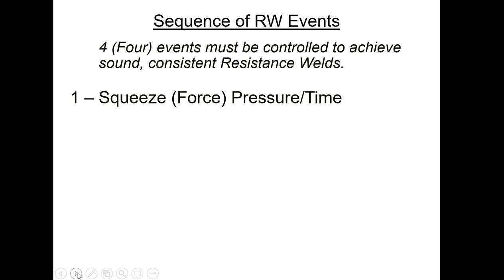How hard you're pushing when current gets applied is critical to this process. And making sure that the current has the right configuration of joint. That is, the pressure and the forces have closed the joint up to where it's very weldable is important to establish from the beginning and to maintain throughout the process. This is where we have trouble with stamping sometimes, where they push back a little bit.